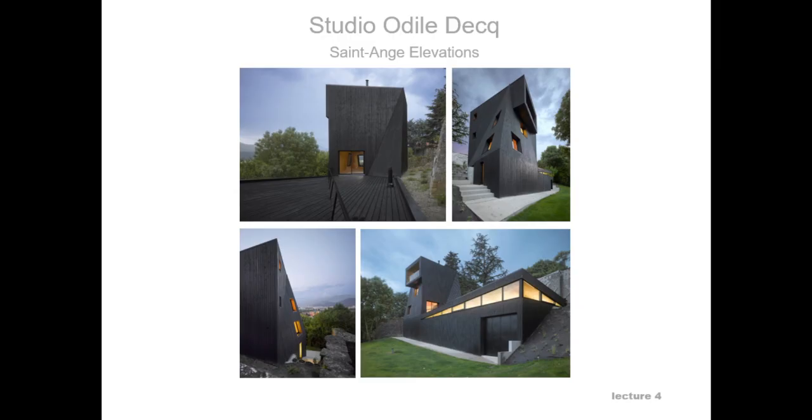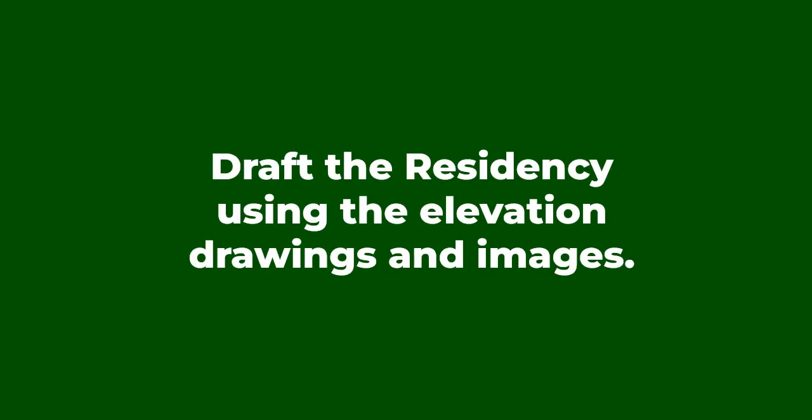So, to the best of your ability, we're going to use this corner on the lower left-hand image to be the datum point now. It's straight. And then turn your model in 4 directions in order to try and achieve the angles we see in the elevation. So we'll spend quite a bit of time doing this before we create walls and floors and roofs out of the form.